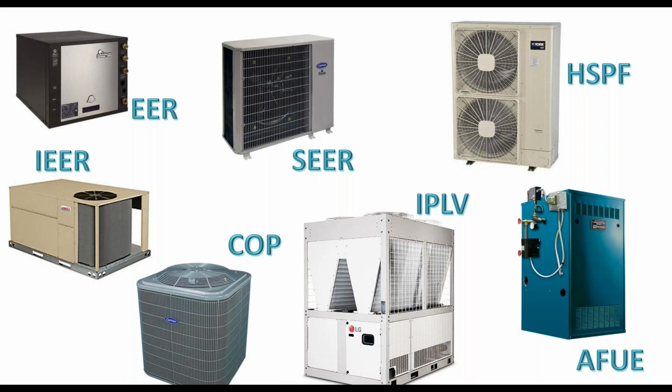It's dependent on the in-lab testing conditions, and all of the different pieces of equipment and the different AHRI standards that they're rated to are different, because each manufacturer gets to test the equipment to the standard that they make up.